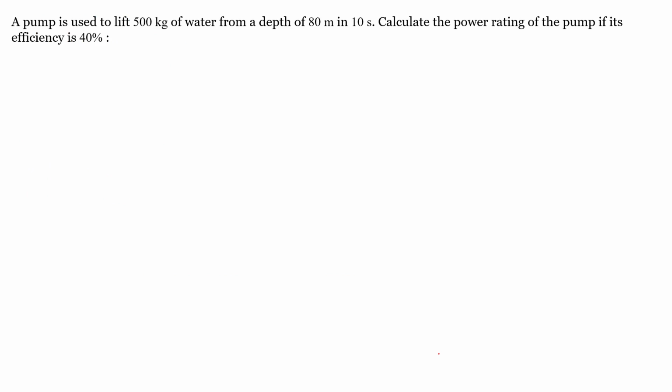Now we are going to discuss power rating. These kinds of questions you've already seen in the week 10 and week 11 classes also, so that's why I am solving these types of questions here. First question: a pump is used to lift 500 kilograms of water from a depth of 80 meters in 10 seconds. Calculate the power rating of the pump if the efficiency is 40%.